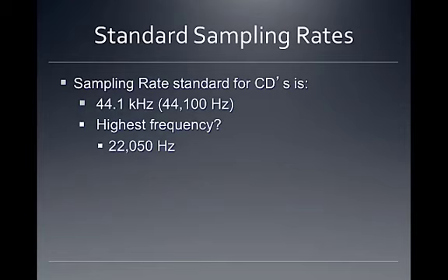We are introducing new sounds into our audio, and at 40,000 times per second, those little snippets of audio become distortion. So we're not talking about long sine wave tones or anything that we hear down in our audio frequency. We're hearing just very small little snippets of this audio, but it's happening very fast, so it ends up being very random distortion, and that is never good. Well, sometimes distortion is good. In the analog world, it's a pretty hip thing.